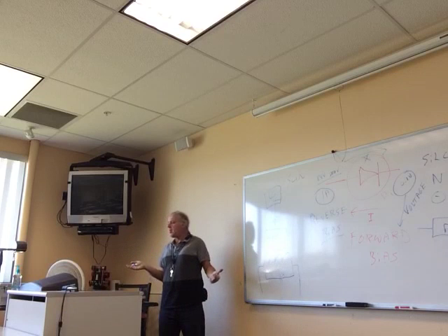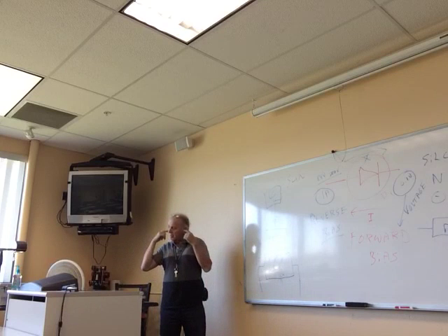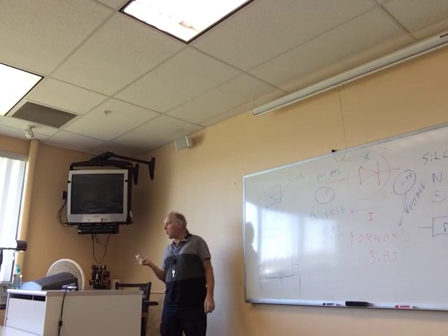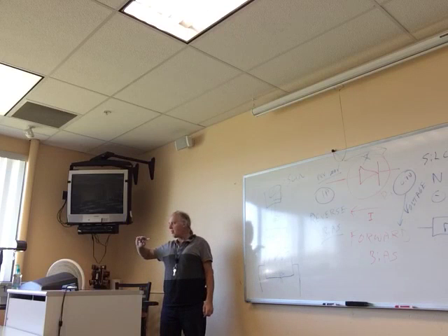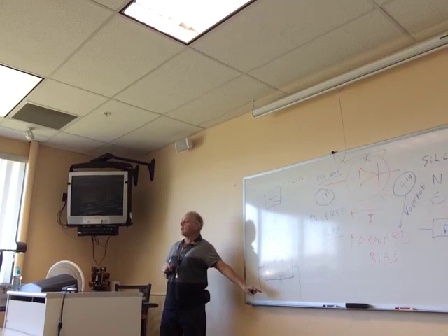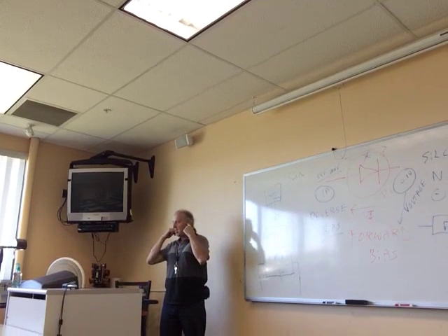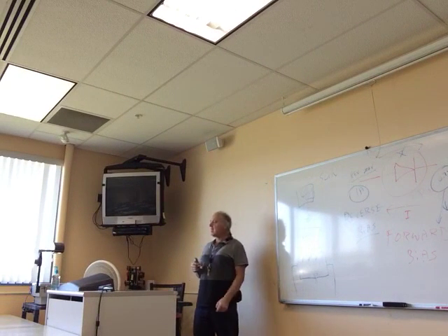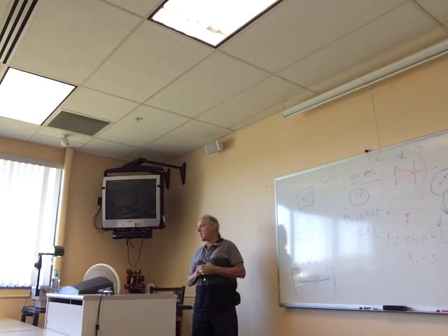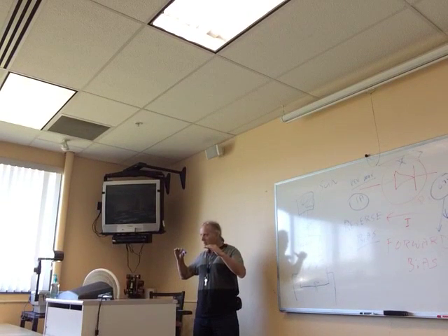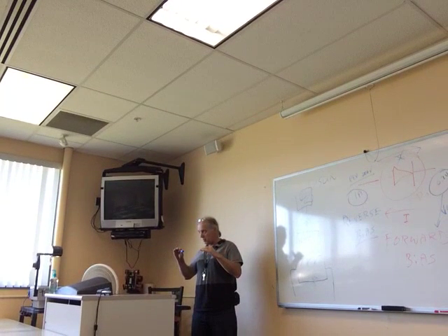If you build a crystal set, a little radio set, that's what you do: you put the diode across there, and at 0.3 volts, it's low enough forward voltage so it'll act as a detector. The silicon won't, but the germanium will, okay? And then you just put a headset on it, and then you can hear a radio station. So they're very popular for things like that. Detector circuits in a lot of different radio equipment have germanium diodes or pin diodes in them, or various other types of diodes, but diodes that have a low forward voltage, 0.3 volts, okay?